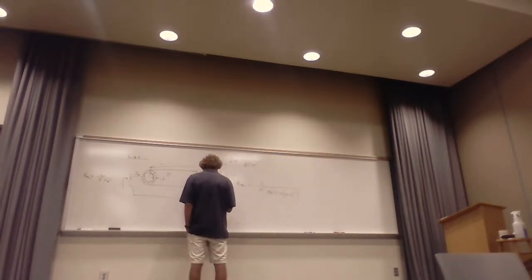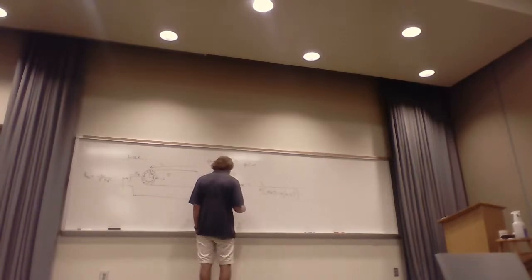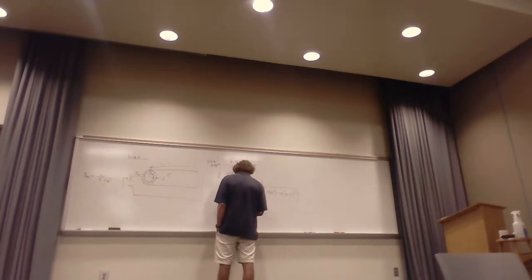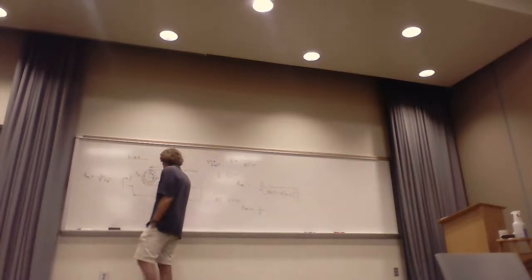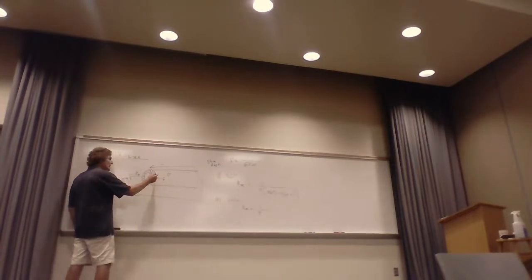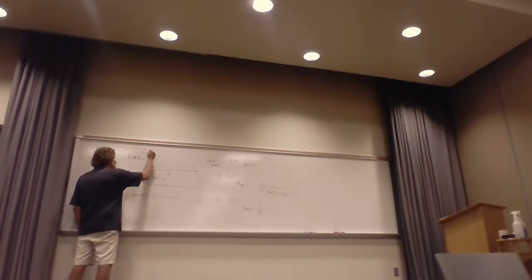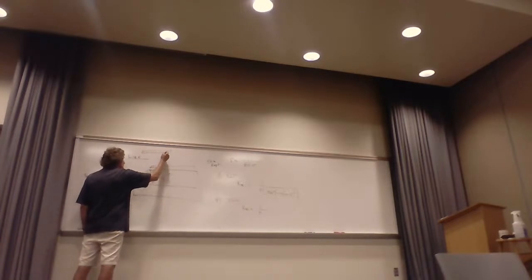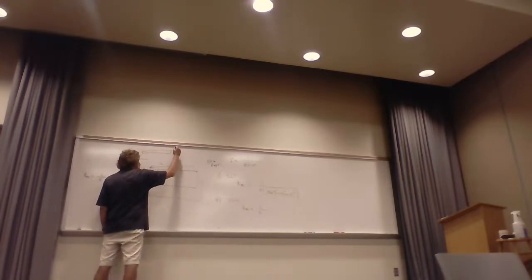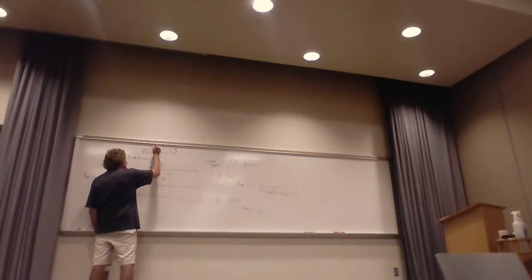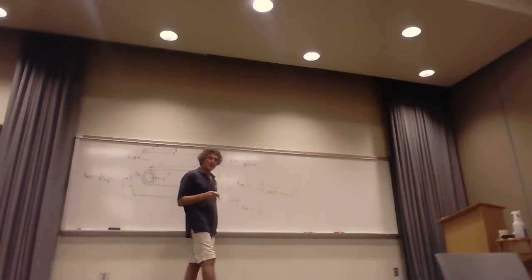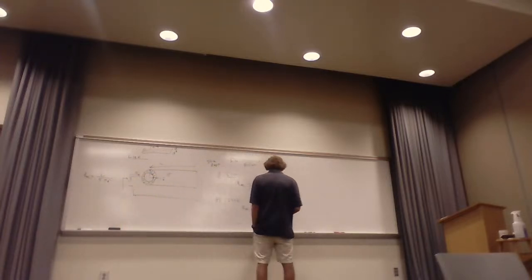And then if and only if the skin depth is much less than a, then we can say that RAC is equal to the length divided by sigma, and then it's just the perimeter. Then you can basically take this one skin depth thick, break it there, and straighten it out so you have a long piece of conductor that has a thickness of 1 skin depth, and its length this way would be the perimeter, 2 pi a, so the area would be skin depth times 2 pi a.